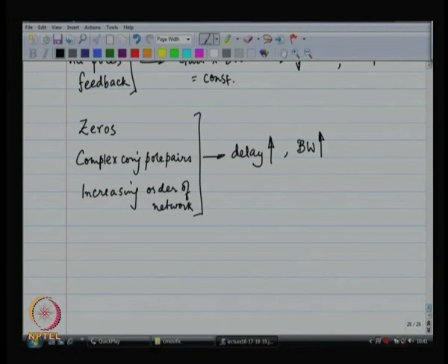There are ultra wideband amplifiers which use a cascaded stage of a lot of transistors, lot of stages, and these particular techniques are used a lot of times in microwave circuits, etc. These techniques also play with the delay. So, you basically say that let me get my signal later, but I want a sharp signal with large bandwidth. So, these are general techniques that are used.